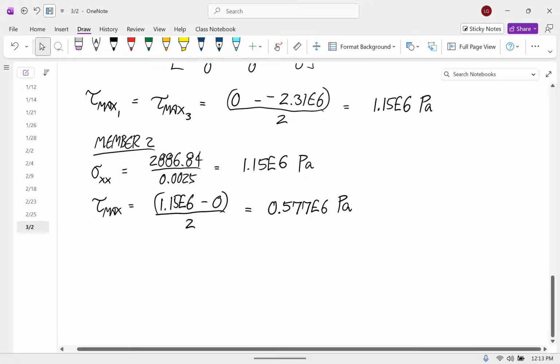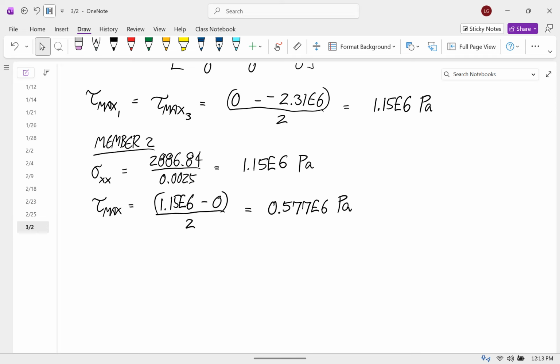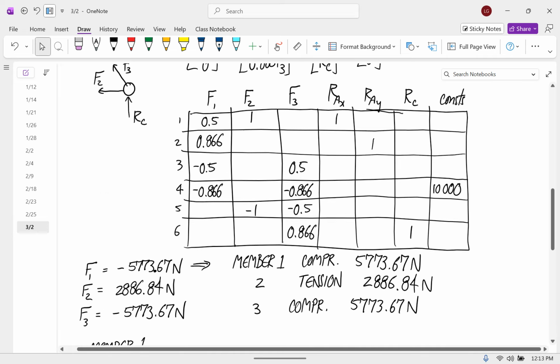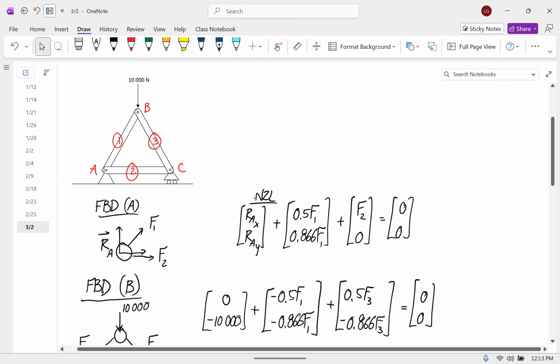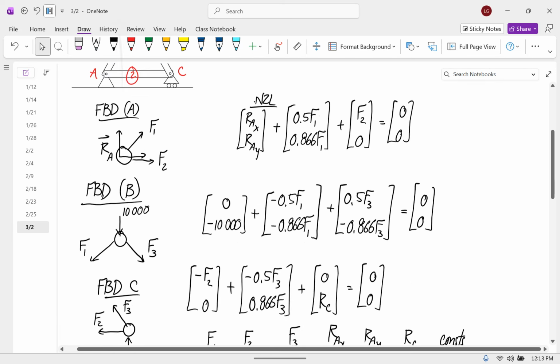And then where do you trust these results? So this is asking about St. Venant's principle. We're making the assumption that these calculations are done by uniform forces, uniform distributed forces at the places where they're loaded. So we don't trust the stuff close to the pins.